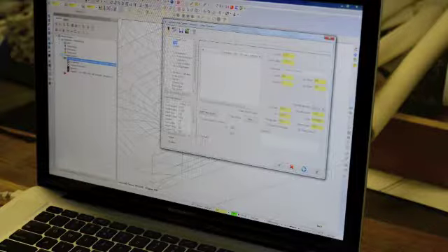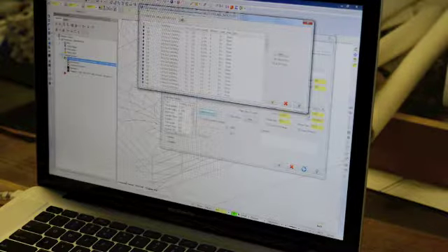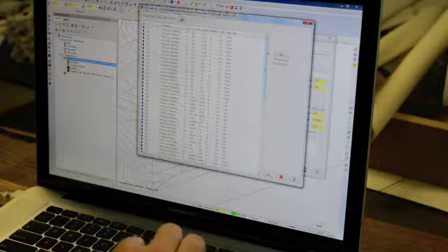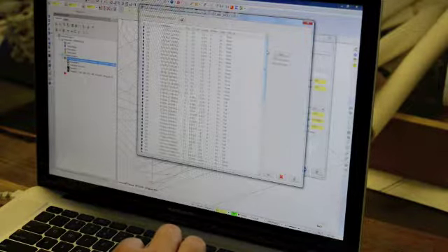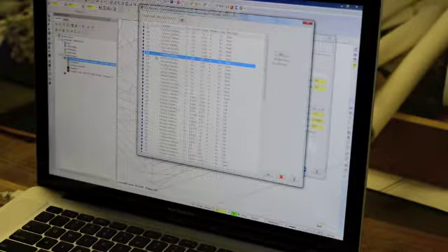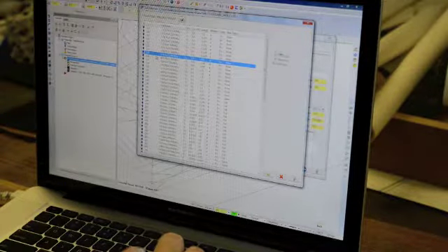So you can go to the tool library over here, and then it's going to pull up a bunch of tools. We obviously don't have all of these, but we do have some. So for example, tool 235 that we use to fly cut, that's over here, and that's where you would select it. For roughing though, and this is where you have to think about what your material is.